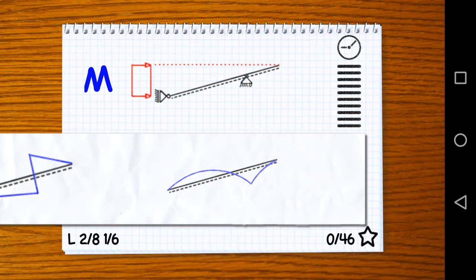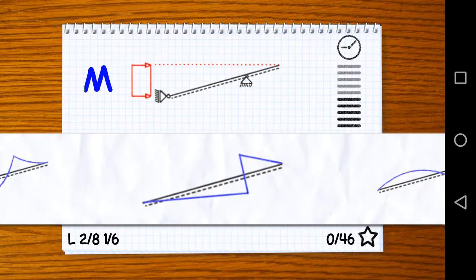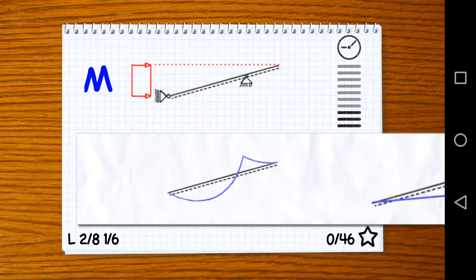Now, we're interested here in bending moments. We picture the beam. We imagine how this beam is going to deform. You can see that last part, that part looking like a cantilever beam, the upper right part, is going to bend downwards, kind of. The tensile side is going to be upward. So this picture here, completely on the right, this solution is wrong. This one could be right, but look, we have a distributed load. The moment can't be linear, okay? So the answer can only be this left one.